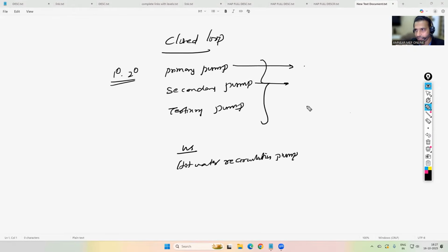So in that critical path, in the longest branch, for hydraulic calculation you should consider the material losses, then the fittings losses, then the coil drop. The coil drop of the last biggest machine: if you have a fan coil unit, an air handling unit, or a fresh air handling unit in the last critical path, the biggest coil, the one with the maximum pressure drop, that pressure drop you have to consider for the secondary pump calculation and add together. Accordingly we can calculate.